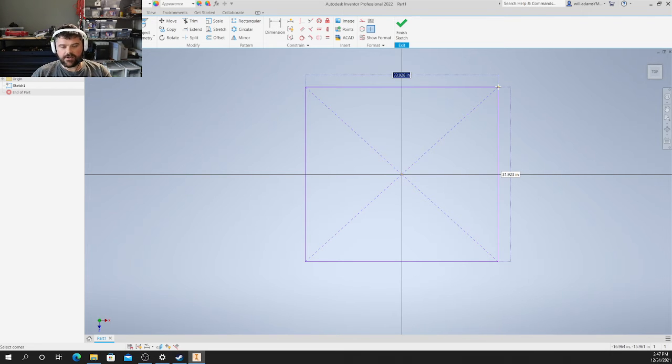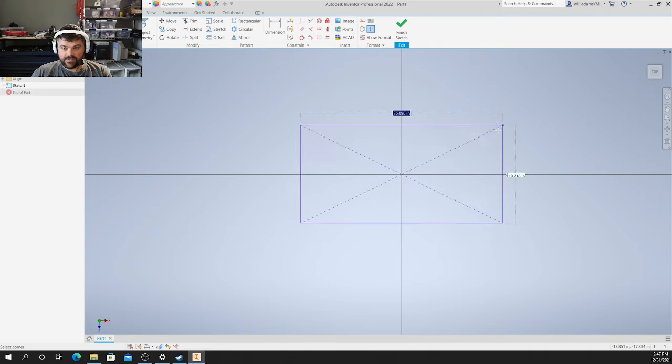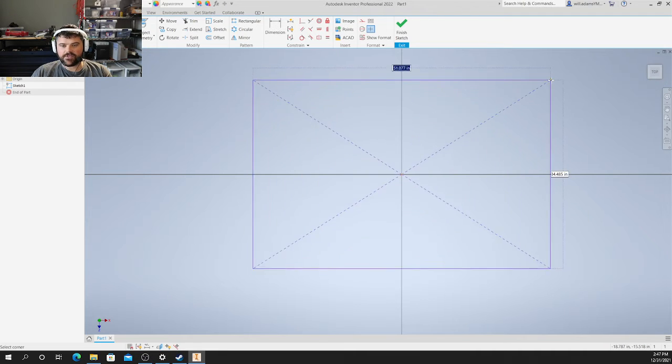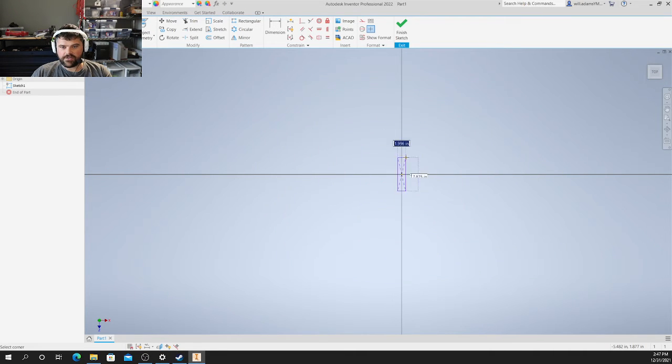The cool thing about Inventor and a lot of 3D modeling packages is you can just type in the units that you want to use right here in these dynamic dimensions. So I've got cursor input. If you see there on the screen, this is called rubber banding. This box is stretching in all the different directions. This concept of seeing the geometry move with my cursor is called rubber banding. And the dimension input there, if I type on the keyboard, you see there's a 1. Now, if I put an M after it, that's 1 meter.